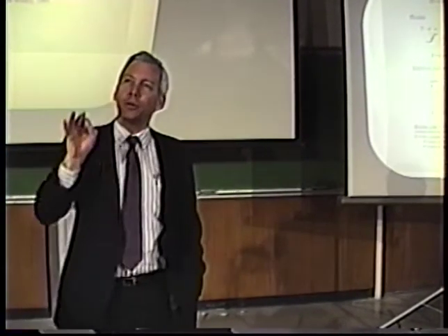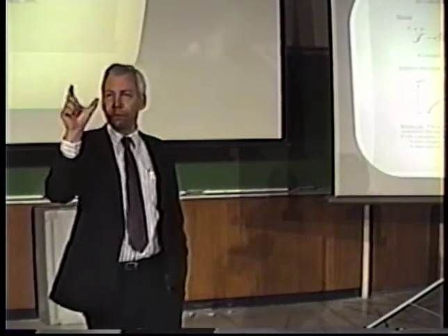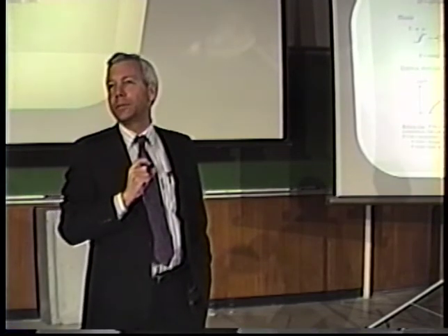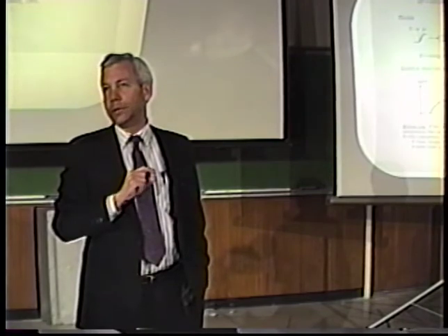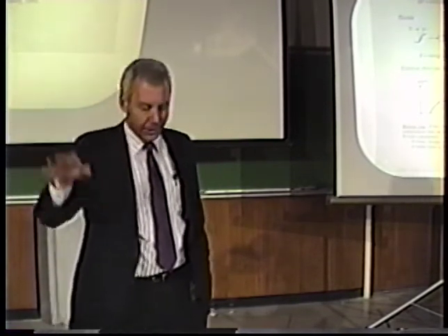If you're a real hardcore engineer, what you will notice is that if I am allowed to make a multiplier that is, say, 5 times slower, it's going to take 1/25th the area if it's AT squared optimal. Does that help? Okay.